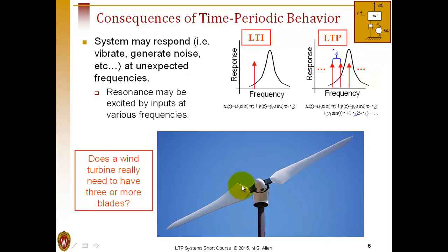By building a turbine with 3 blades, and if the blades are all identical, we can approximate the turbine rotor as a whole as an isotropic kind of disk. And so there's little concern for time periodic behavior of the turbine unless we have damage to a blade or the blades are different due to manufacturing defects and tolerances, which, by the way, they always are.